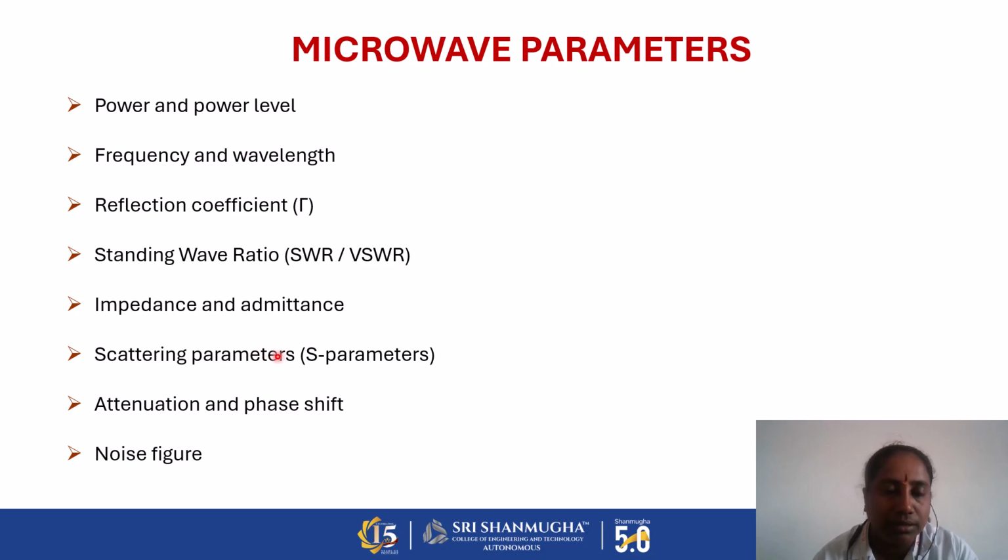And scattering parameters, so it comes under the reflection and transmission coefficient. And by using the power method, we can calculate both attenuation and phase shift of the microwave measurement. And next one, noise. By using the noise measurement, we can calculate the noise figure as well as the signal to noise ratio, that is SNR.